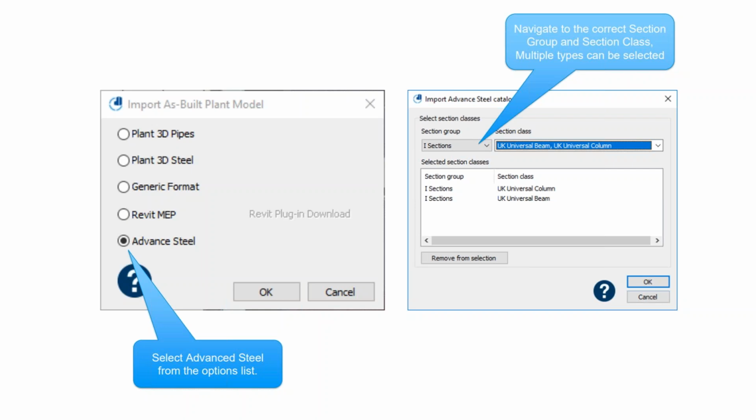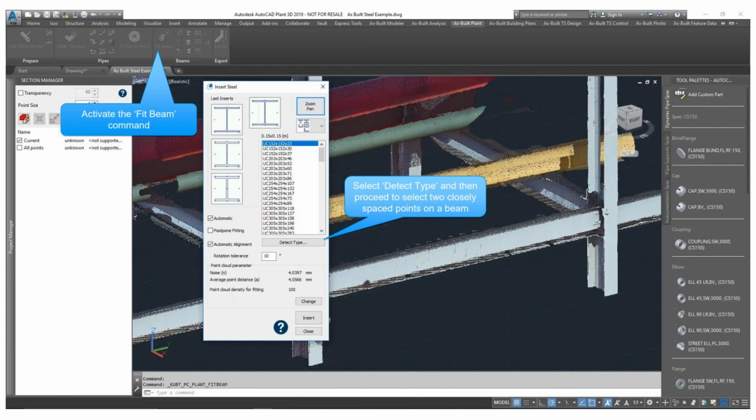And we could select, as per our current design criteria, I sections belonging to certain country codes, whether it is UK sections, use your UB sections, and also define the sizes. Now, once you have defined the standards which you're trying to use,